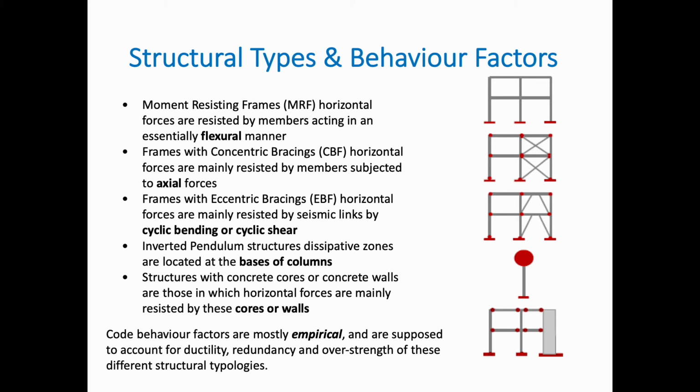And we have the inverted pendulum structures, which are located at the bases of columns, and we haven't discussed that much. Unfortunately it is one of the things that we did not have time to go through. And we have the structures with concrete cores or concrete walls, and again the cores and the walls are resisting the lateral forces. The code behavior factors are mostly empirical and are supposed to account for the ductility, redundancy, and overstrength of these different structural typologies.